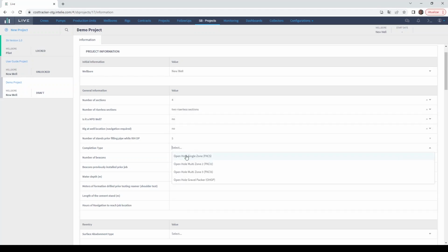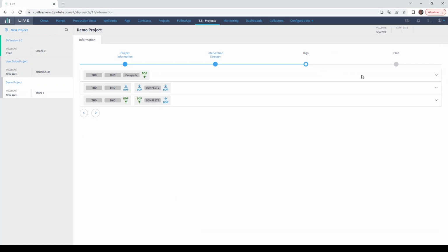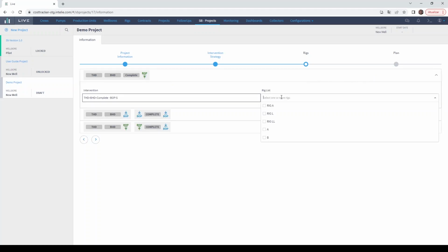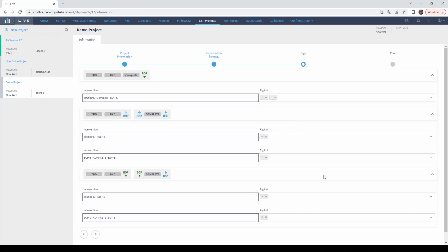At this point, the user will be presented with questions that will guide their choice of well design and planning, from basic well geometries and other operational questions to selection of different well construction strategies. As a last stage, Sequence Builder allows the users to configure multiple rig performance parameters, such as drilling and tripping speeds. This will provide the required information to estimate the duration of each operation and of the whole project. The user can add as many rigs as desired and set them to any well construction strategy.